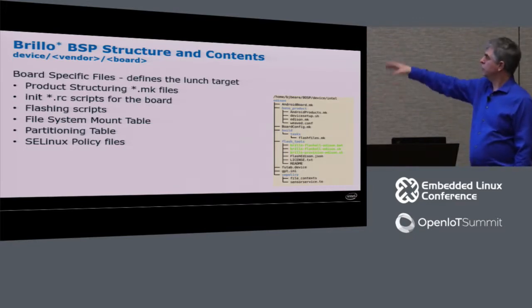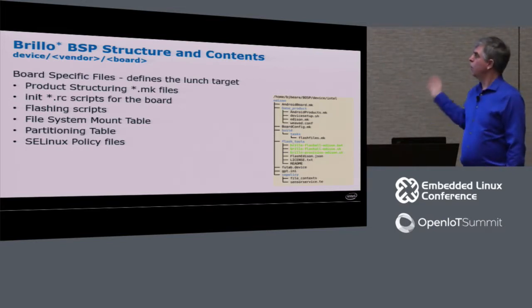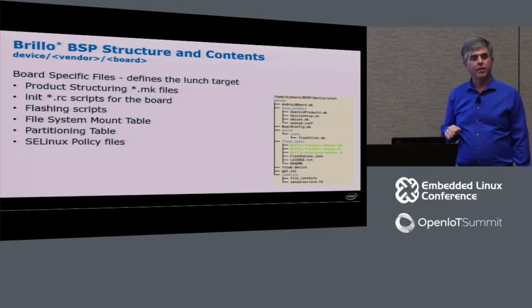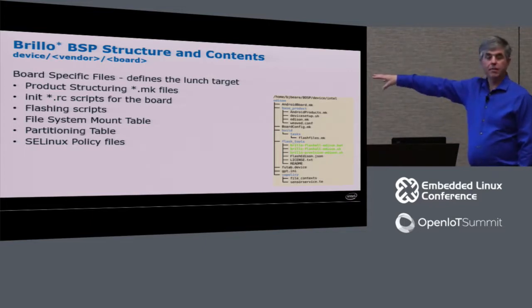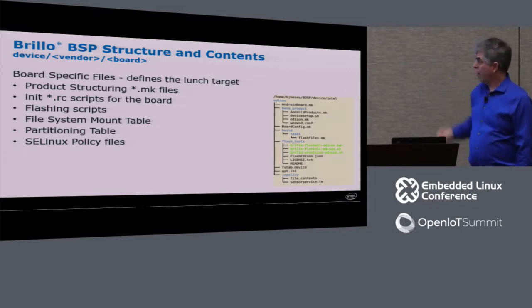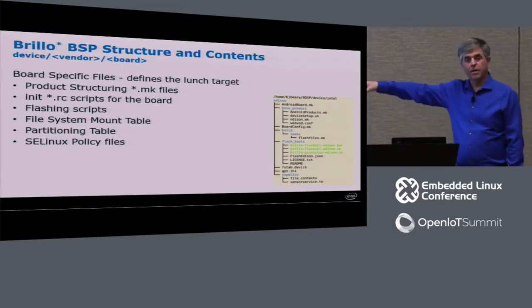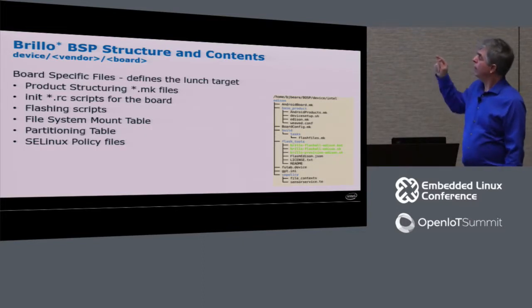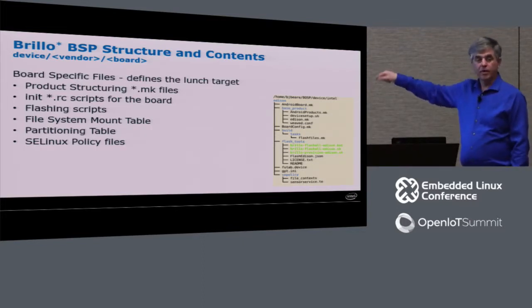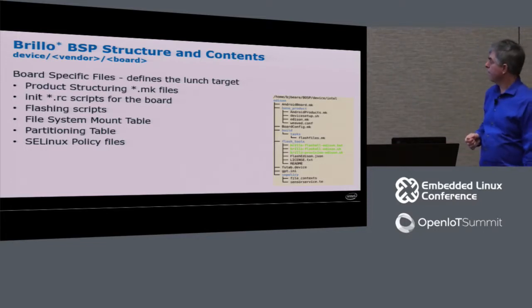We don't put a lot of source code in there. We really put control files in there. The source code we try to put in the peripheral directory. We try to put binaries in the vendor BSP directory, and we try to put really just some script files and makefiles and similar things in here. The gpt.ini is our partition table, for instance. We put it in here on our devices so the user can change the GPT and the partitioning on their device, for instance.